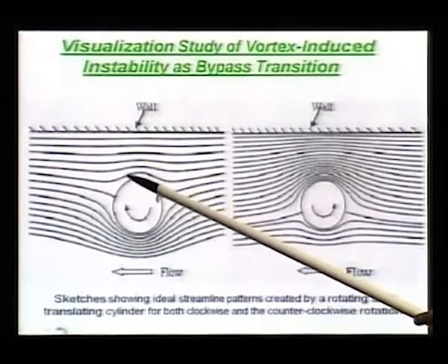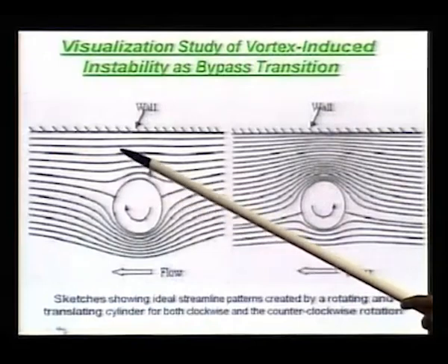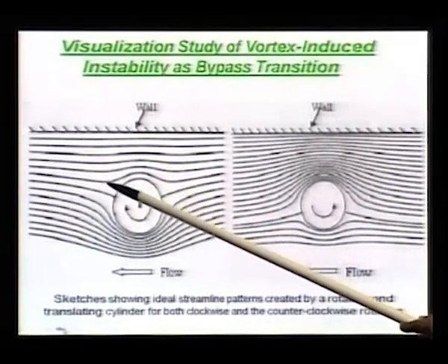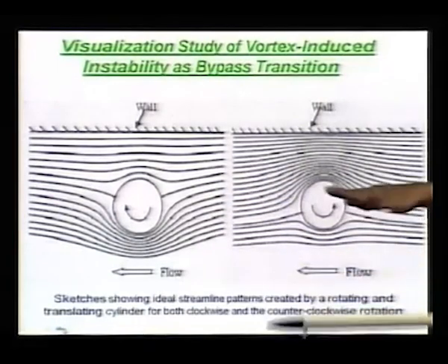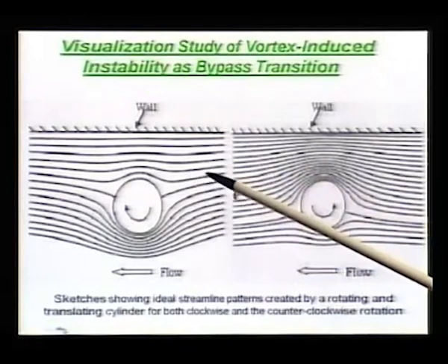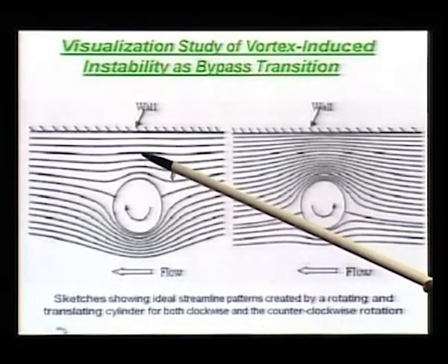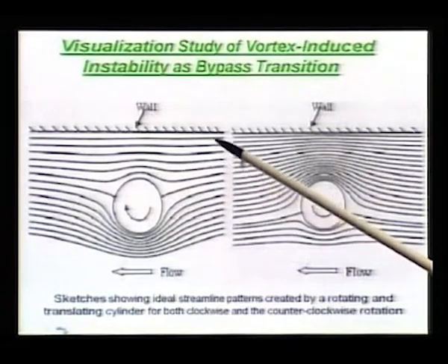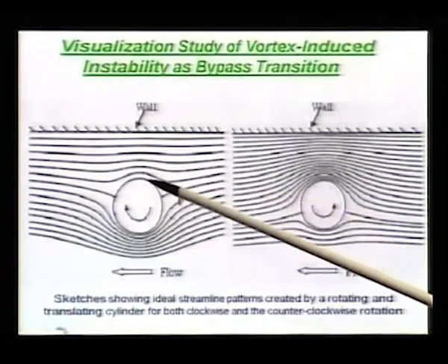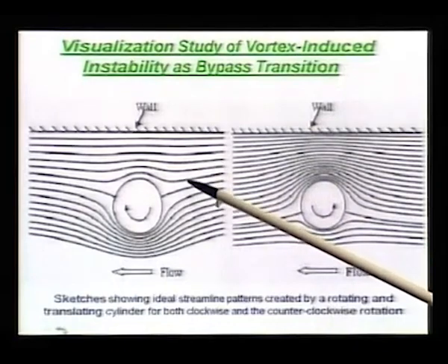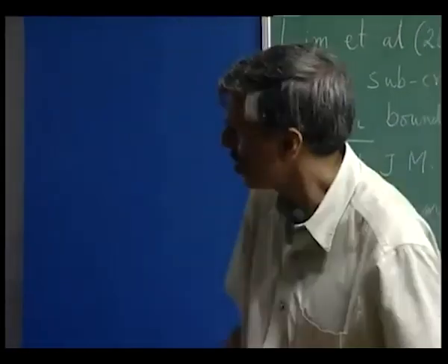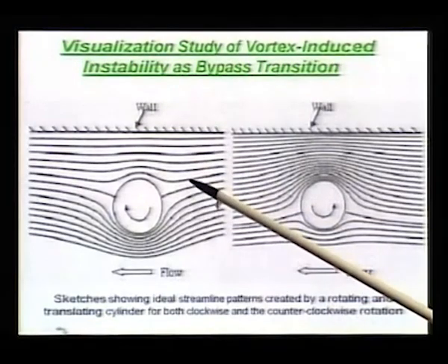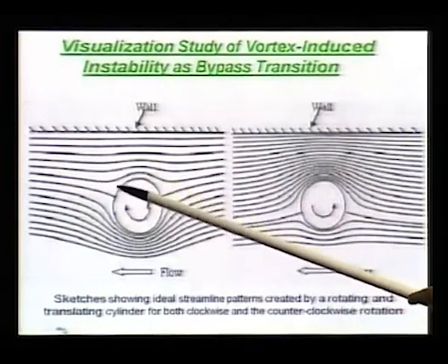This is here, behind the cylinder. You see, here it goes rapidly. Here also there is a kind of a divergence, streamline divergence, but this is more like straight. Whereas here, even though it was adverse in this part, that is followed by a favorable pressure gradient. So, even if the flow was becoming unstable here, but when it comes very close to the cylinder itself, you actually again impose a favorable pressure gradient. So, that thing is created there, but that is again followed by a rapid streamline.